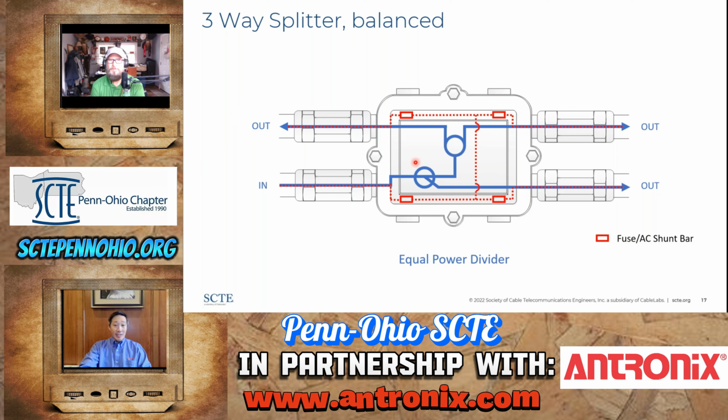And you can see the configuration of this directional coupler is very different than the tap, whereas the coupled port on the directional coupler is going to be in the output here. And when we show a tap a few slides later, you'll see this block diagram being a little bit different, but it is a directional coupler and a splitter as well. Yeah, it'll be the opposite. The through leg will go to the out, and the down leg then would go to the splitters. Exactly.